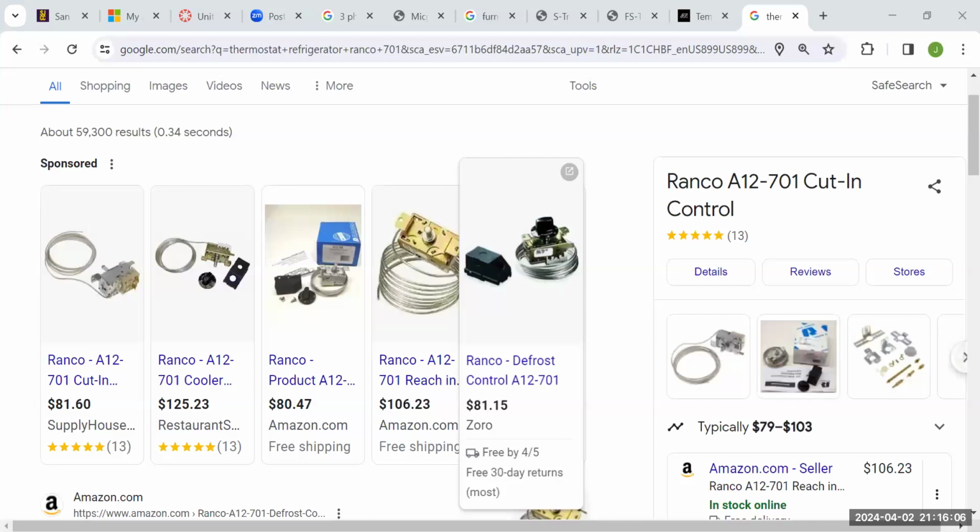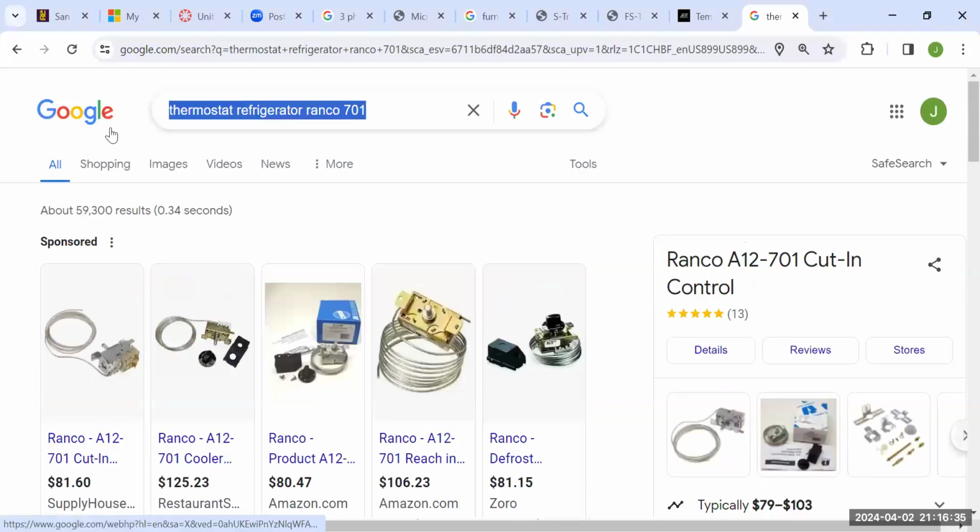So inside of the control, instead of it being a thin metal disc that's going to warp up, they have something that looks like an accordion. And now when we increase the pressure on it, this thing has a lot of movement. It could really expand a lot. And then if we decrease the pressure, it could really constrict down quite a bit there. So if you look at like a high pressure switch,